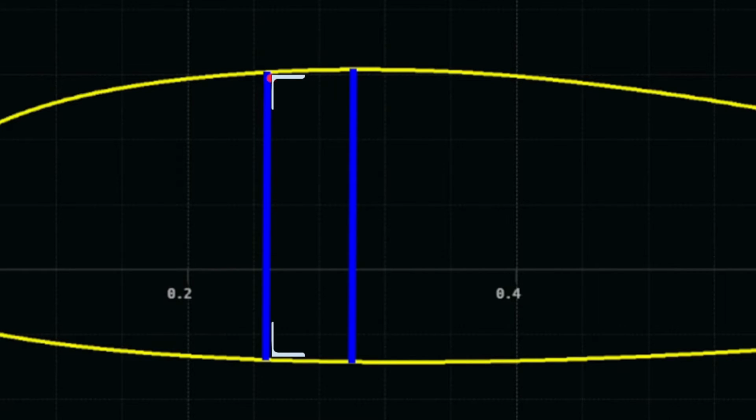So if I do that, that spar cap will be flat here, but we have a curve to our airfoil. So if I rivet the aluminum skin down to the spar cap, we're going to have a flat spot here, and then it's going to come back up, and then it's going to reach the thick spot. So that's going to deform the airfoil. And same thing on the bottom. It would flatten out that airfoil right there where I would rivet the skin to the spar cap, and I really don't want to do that.